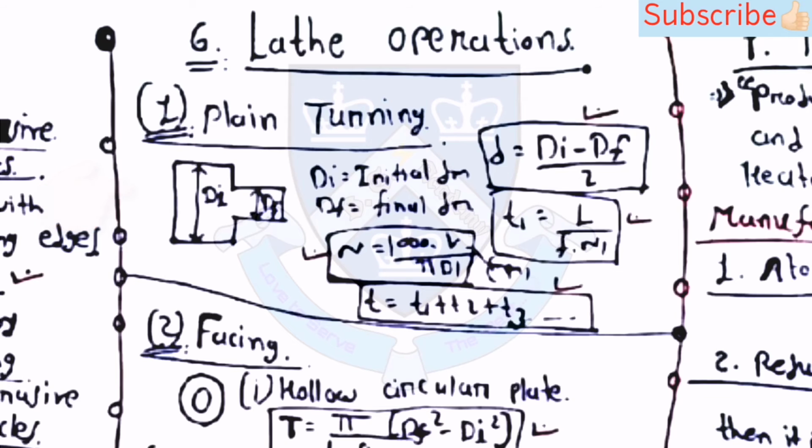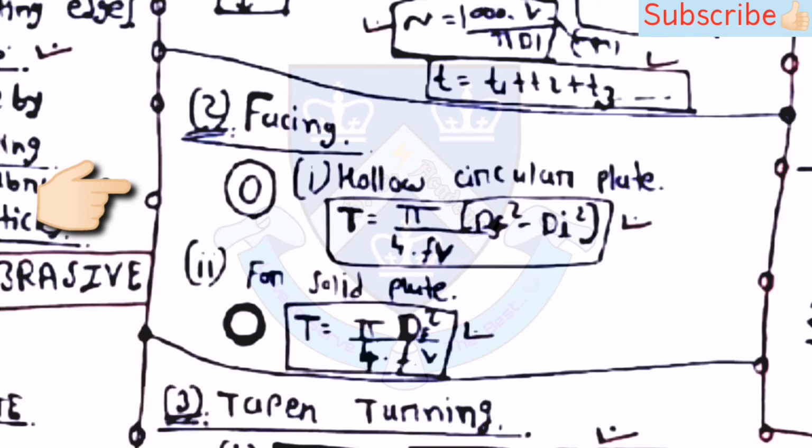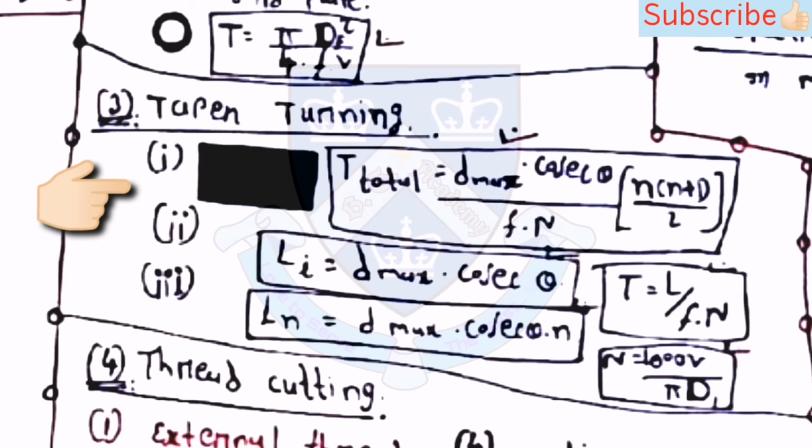plus T3. Then for the facing process, T is equal to pi upon 4 into Fv into df square minus di square. Then for solid plate, T is equal to pi into df square upon 4 into Fv. Then for the taper turning process, capital T total is equal to d max into cosec theta upon F into n plus 1 by 2. Then Li is equal to d max into cosec theta.